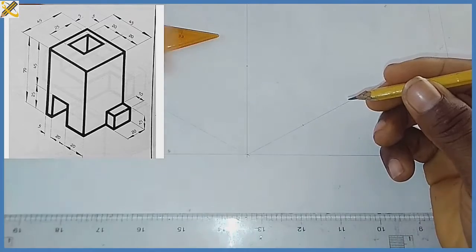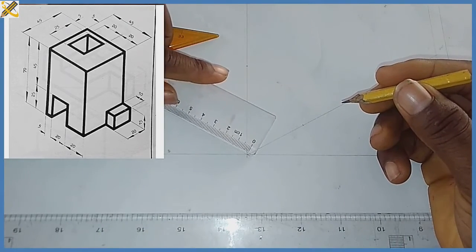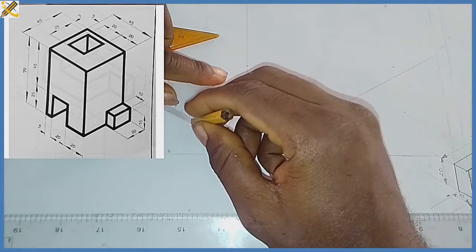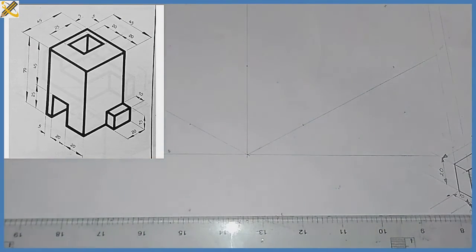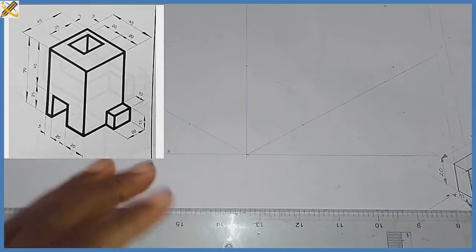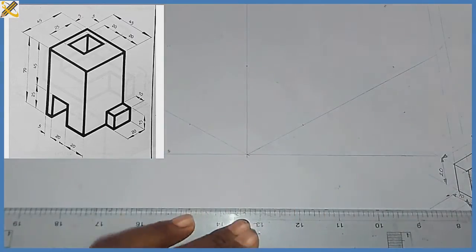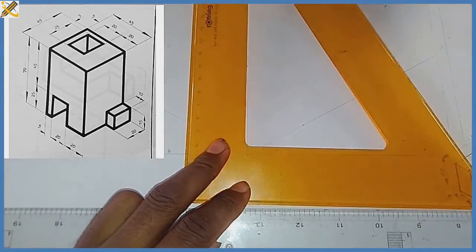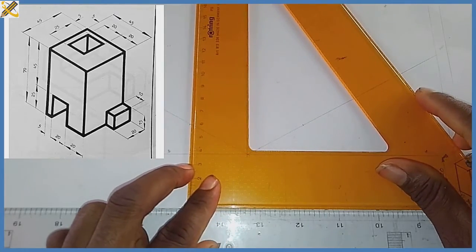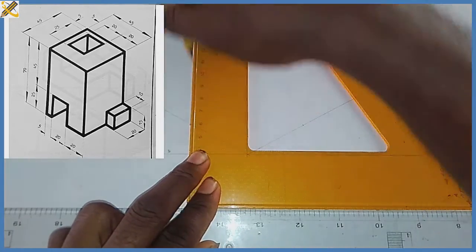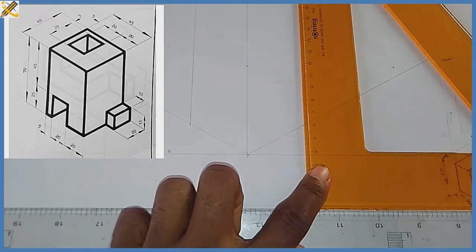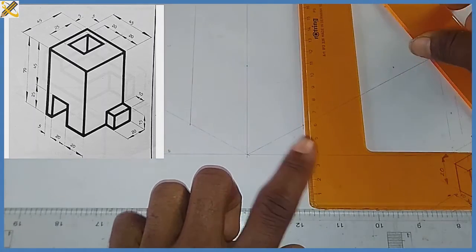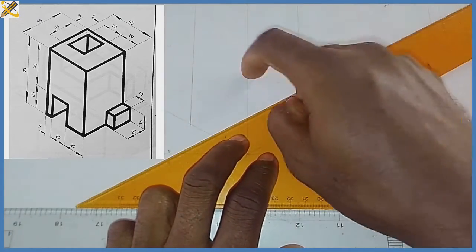Okay, so towards this axis also is 45 mm. So from here, I measure a mark of 45 mm, which is that. So the next procedure is the mark of 45 mm towards this axis, and this axis will be projected upwards. All right. So right here, I project it upward. Right here, I also project it upwards.